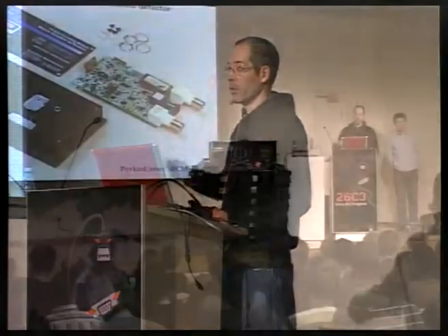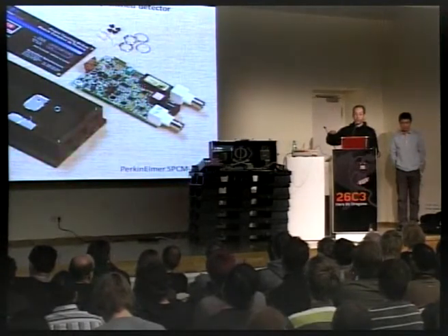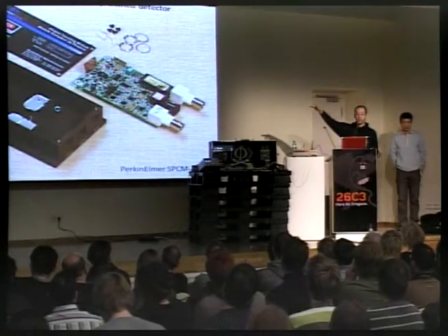That means that when you have an avalanche, you need to quench the avalanche. You need to lower the bias voltage of the diode below breakdown to quench the avalanche. And it can be done passively, as you saw on the first detector, or it can be done actively, like with this detector, with some electronics.